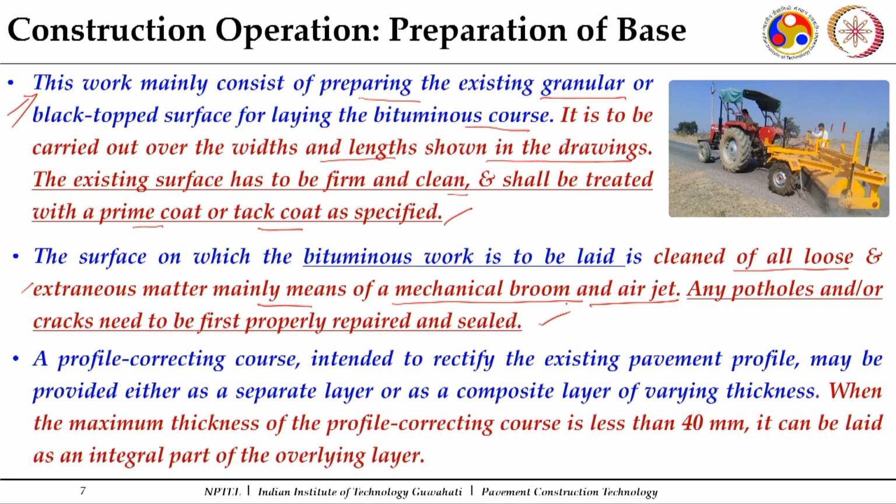This is an important exercise: even if small cracks are observed or some potholes are there on an existing pavement where we are putting up a bituminous layer, those potholes should be filled up with designated proper material, cracks should be filled up, and then this overlay exercise has to be taken up.